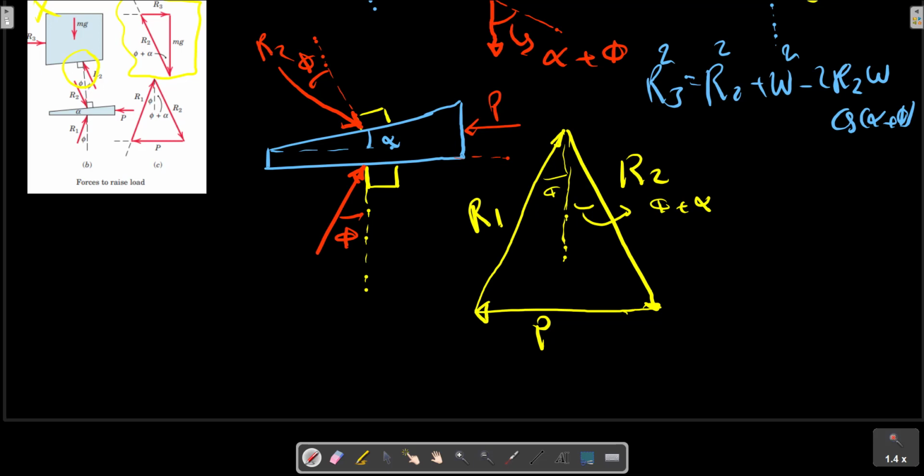Part A of the figure represents impending slippage at the upper surface, and part C represents impending slippage at the lower surface. In order for the wedge to slide out of its space, slippage must occur at both surfaces simultaneously, otherwise the wedge is self-locking, and there is a finite range of possible intermediate angular positions of R1 and R2 for which the wedge will remain in place.